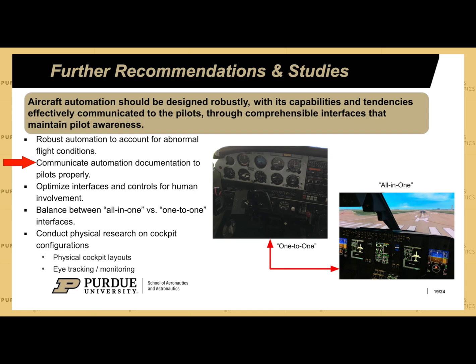Moving on to the cockpit, the avionics interfaces represent the means by which information is exchanged between pilots and aircraft systems. As such, as long as humans remain at the center of cockpit operations, automation must be optimized for human tendencies and behaviors. One possible method is to design automation that is controlled or displayed in the same way as the aircraft is flown without automation, such as manually setting the throttle levers before engaging autothrottle, or having the throttle levers physically move as the autothrottle modulates the thrust setting. Interfaces such as control panels should have distinct functionalities, or, if containing multiple functions, should have clear procedures and indications for their correct operation to mitigate mode error.